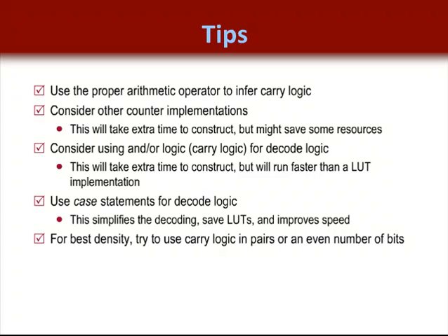Consider using and/or carry logic for decode logic. This will take extra time to construct, but will run faster than a LUT implementation because it will take advantage of the carry chain. Use case statements for decode logic. This will simplify the decoding, save LUTs, and improve speed. And really the most key thing is improved speeds by tending to synthesize to more parallel logic. And for best density, try to use carry logic in pairs or in an even number of bits.